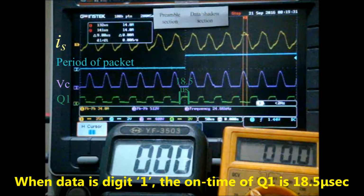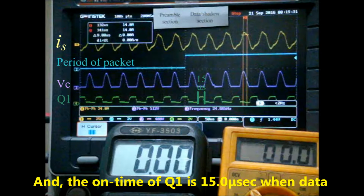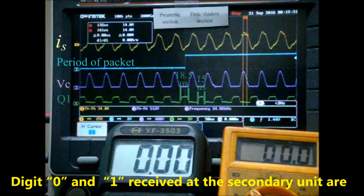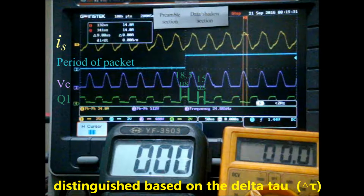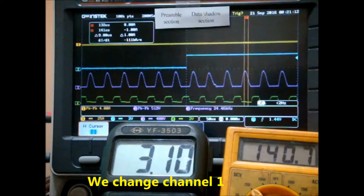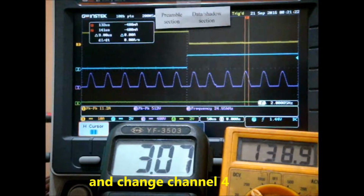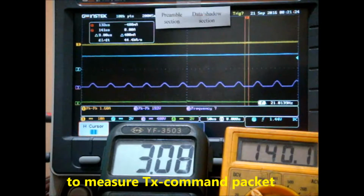When data is digit 1, the on time of Q1 is 18.5 microseconds, and the on time of Q1 is 15.0 microseconds when data is digit 0. Digits 0 and 1 received at the secondary unit are distinguished based on the delta tau. We change channel 1 to measure the RS command packet, and change channel 4 to measure the TX command packet.